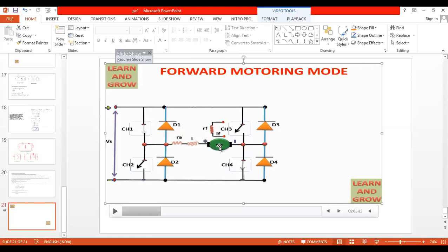These words you have to keep in your explanation, which many textbooks have failed. You can study any power electronics textbook. When the inductive load or especially the motor is present, these words are missing. But what industry people require, this explanation they require. When the supply is on, we have mentioned the direction of the current. During this process, the inductor energizes. This will be the positive and this will be the negative terminal for the inductor.